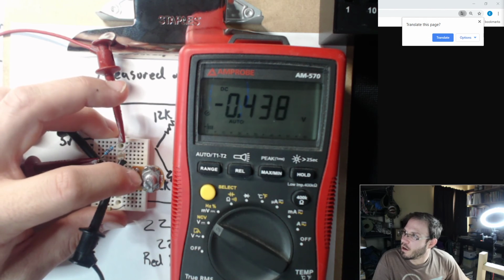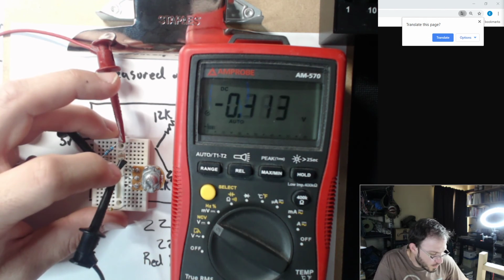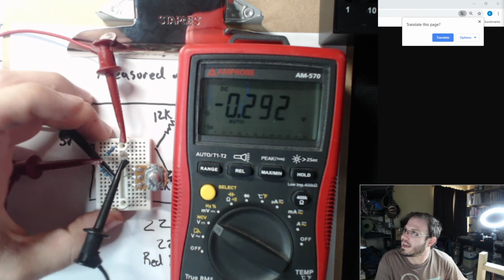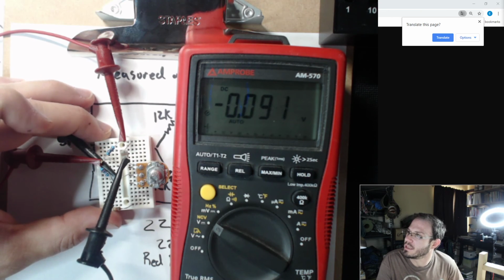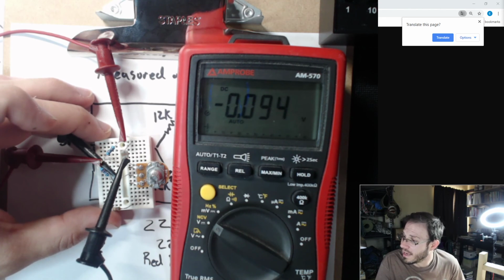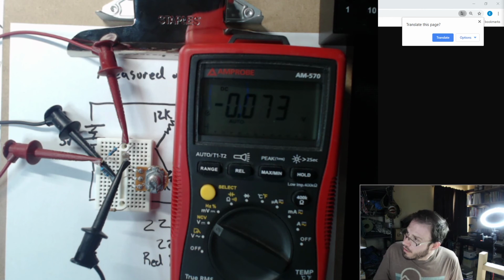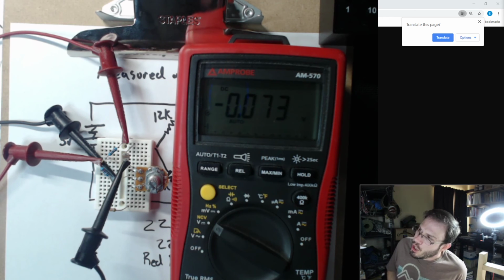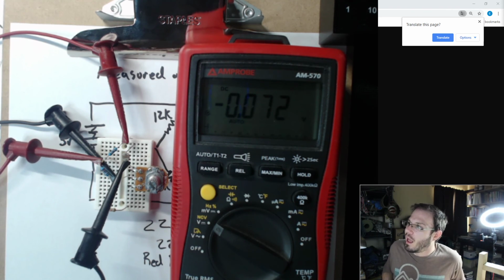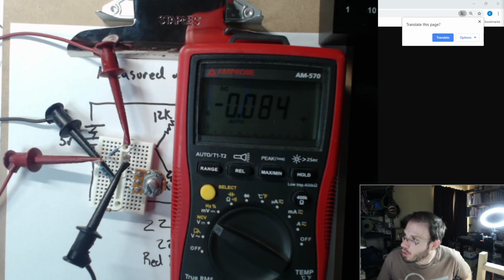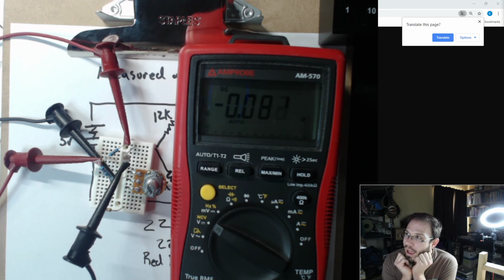And I use this variable potentiometer in order to, we would call that nulling, where I set its baseline to be about 0 volts for my intended application. Okay? So the bridge circuit for measuring an unknown resistance is kind of a moot point because we have multimeters that can do it very well.